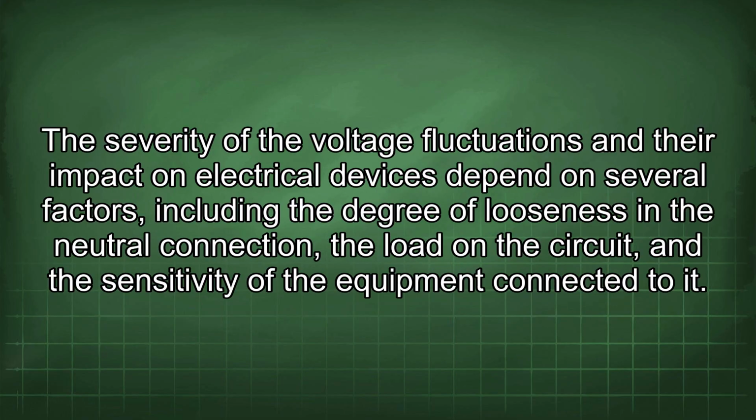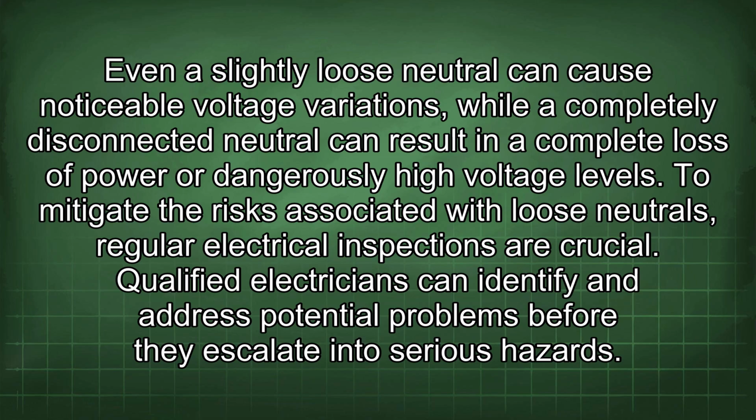The severity of the voltage fluctuations and their impact on electrical devices depend on several factors, including the degree of looseness in the neutral connection, the load in the circuit, and the sensitivity of the equipment connected to it. Even a slightly loose neutral can cause noticeable voltage variations, while a completely disconnected neutral can result in a complete loss of power or dangerously high voltage levels.